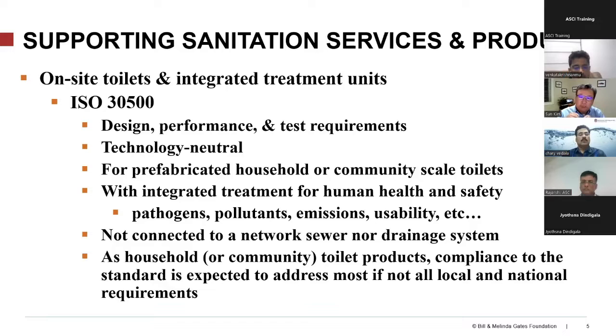In fact, the effluent of compliant systems, depending on whether it meets category A or category B, could have unrestricted use, unrestricted discharge, because it meets a certain level of COD, or possibly restricted use, whether it's watering gardens or underground discharge if it meets category B. But the key in both cases is that the pathogen reduction is such that it is safe for humans.